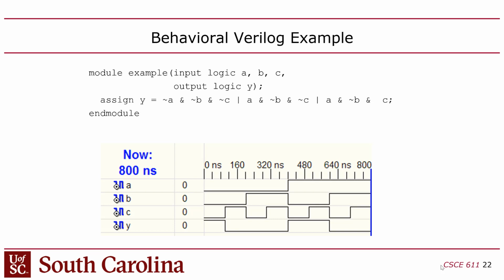And then when you simulate it, you're going to generally look at this as a timing diagram, where the horizontal axis is time, and then you'll have ones and zeros there, and then you have a cursor that you can move around. In this case, we're looking at every possible combination of inputs and the corresponding output. Because it's combinational logic, when you test this circuit, you're looking at the instantaneous values of the inputs and the outputs. There's no memory involved here, so we're just looking at whatever the output is, and there's corresponding inputs for that at that moment in time.